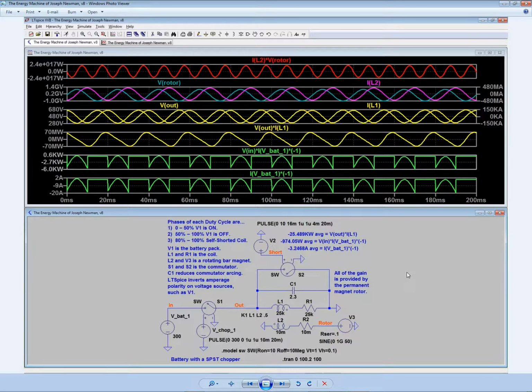You raise the voltage, then you automatically raise the RPM if you raise the voltage on the coil. And that was the other thing. I had to limit myself to the RPM, which I think was 136 RPM. So I just tweaked it so that it would be a 20 millisecond duty cycle.